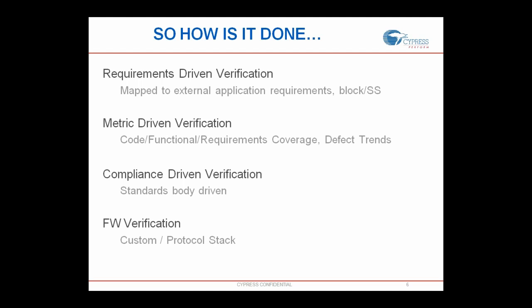at least we should have a plan to validate it in emulation or FPGA platform. And because we are putting so many things in a single chip, firmware becomes an extremely important aspect. Protocols like Bluetooth have a huge firmware stack, which implements a lot of functionalities specified by the protocol. My experience tells me that many times we have silicon in hand, but we are not able to sell it because the firmware is not ready. So therefore, we have to verify the firmware before even taping out. I would even put the bar that high. The reason: the handshakes between the hardware and firmware, if not addressed properly during verification, are going to cause a major headache.